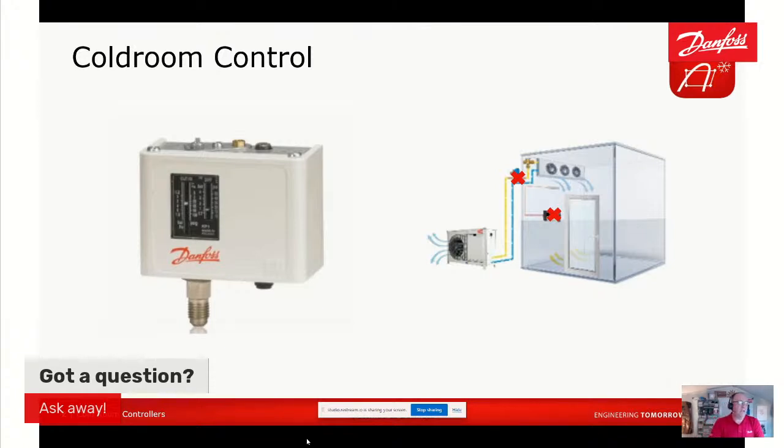So in the very beginning, when I was 16 years old, starting out in the trade, a very, very simple way of controlling the room temperature in a cold room. You didn't use a controller, you didn't use a solenoid valve, you literally just used a LP switch. And that LP switch controlled the pressure in the system, and that pressure equated to a temperature. So as the pressure reduced, you would cut out your LP, stop the compressor, and that was your basic control. So very, very simple.